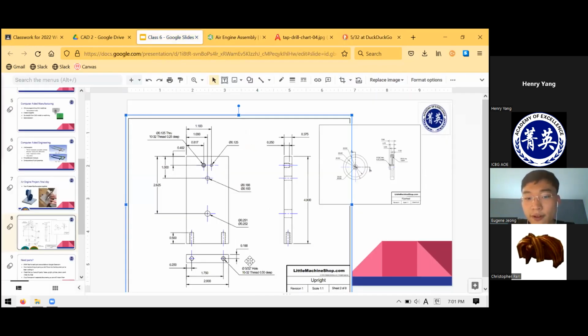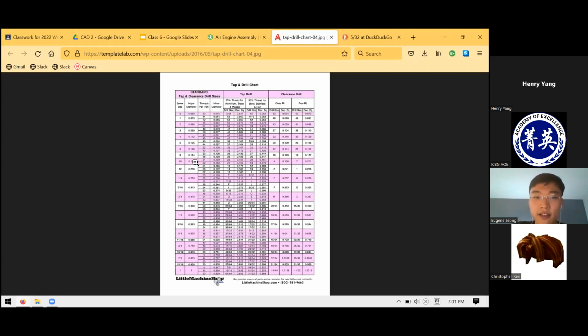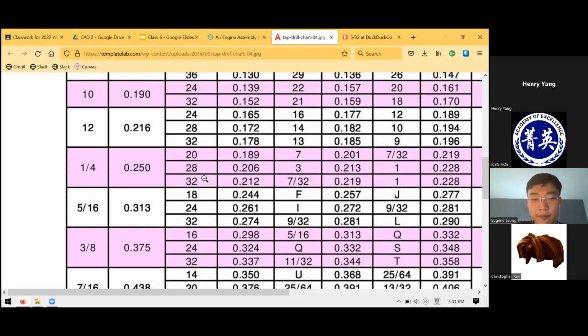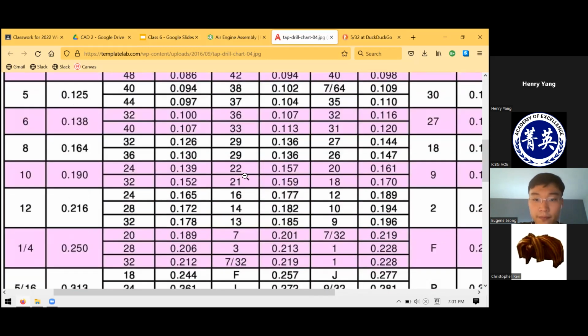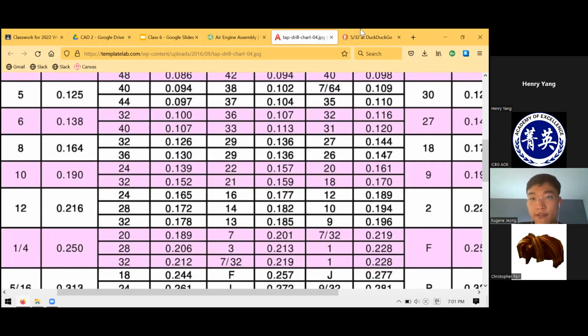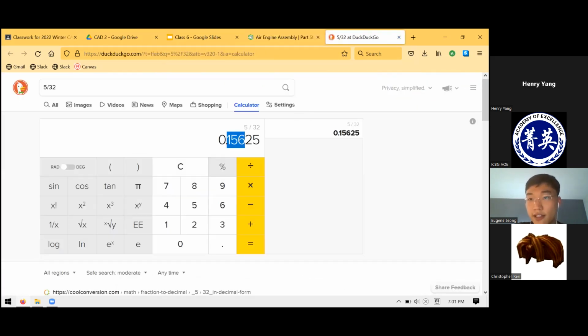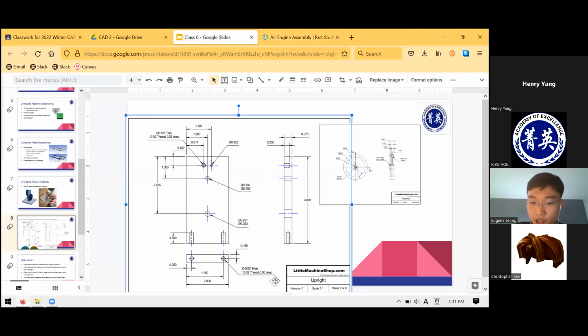So if you're making this in real life, what would happen is you drill in 0.5 deep using a 5/32. And these tap charts aren't absolute. Basically you should follow them, but there's so many different types of drills in real life that you can usually get away with using a drill that's very close to the size you're using. So in this case, instead of using a 0.159, they're using a 5/32. I have a question. Let's see. Yeah, so instead of a 0.159, they're just saying use a 5/32, and that's your pre-drill. So your pre-drill goes in half an inch.